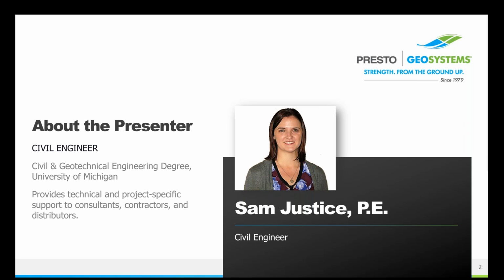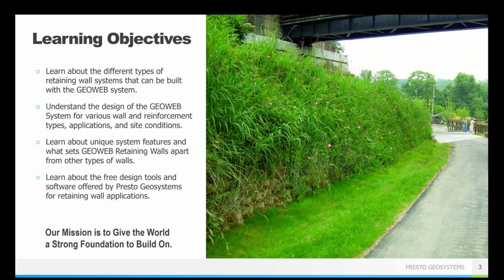So we are going to be covering both steep slopes and retaining walls today. The GeoWeb system works for both types of applications, and the big difference between the two is going to be the batter of the wall, or that slope face angle. We are going to get into details about each one, so don't worry about the specifics at this exact moment.